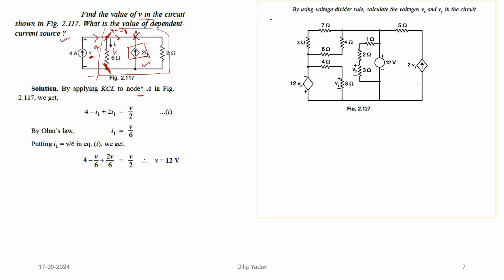So by using nodal analysis, say this is the voltage VA, VB, and the resistors are connected across this terminal and this terminal. The sign convention is really important. If I say this is I1, that is going to flow between this. If it is I2, so it is I1 minus I2.